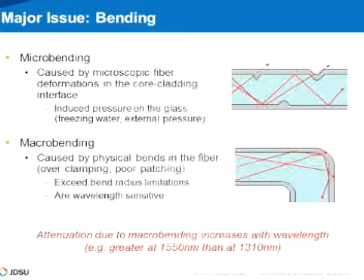Microbends are a little bit more common because in the past people would zip tie those cables, and that would change the fiber. One of the contractors showed me a picture the other day where the fiber was positioned so that when he closes the patch panel, it pushes on the fiber and bends the radius, so the fiber would not perform properly.